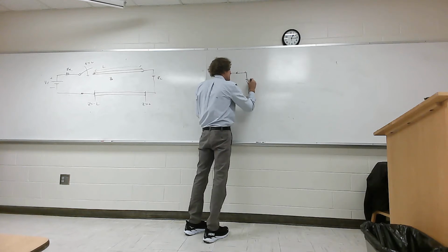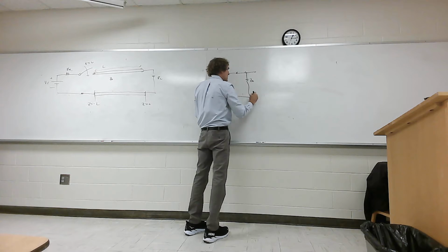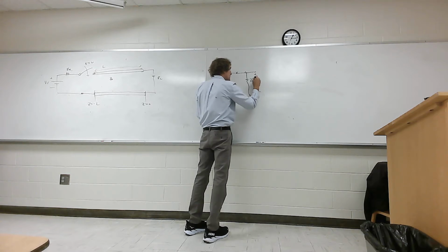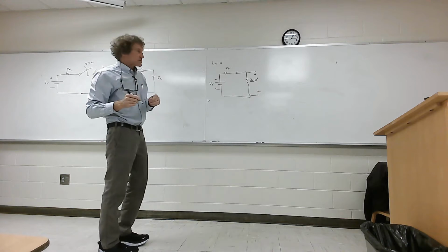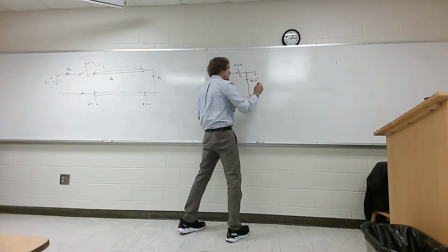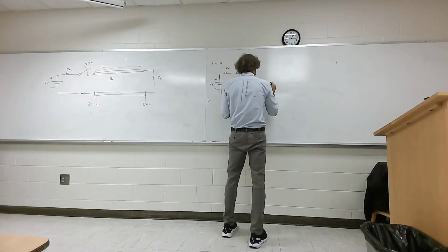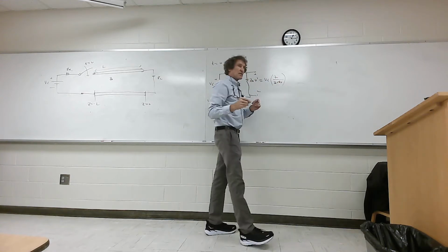So this would have impedance of Z0, and then you can get what's called V prime. You can get the voltage right here that's going to occur at the instant that switch closes. This would be at t equals 0. And that value V prime is simply going to be Vs times Z0 over Z0 plus Rs. That's your starting point.